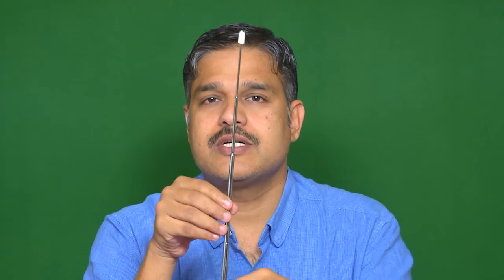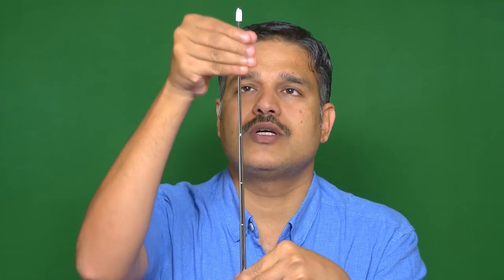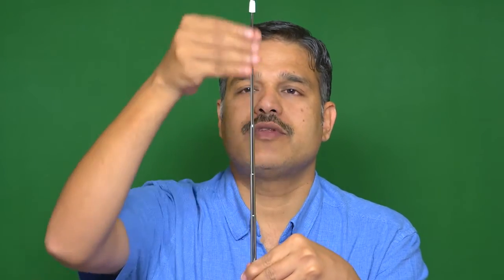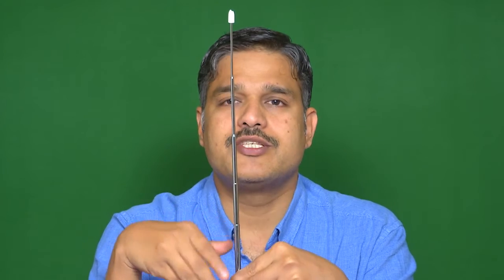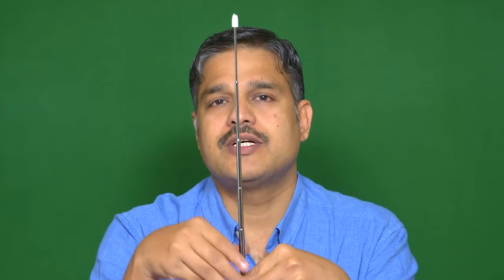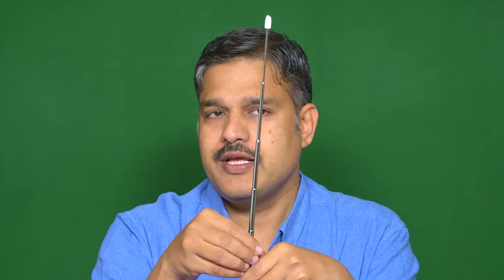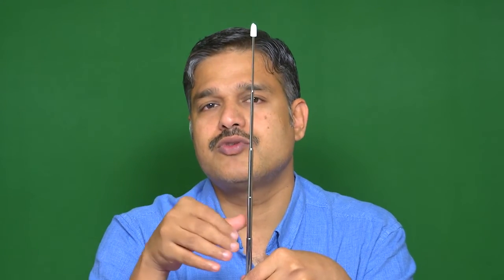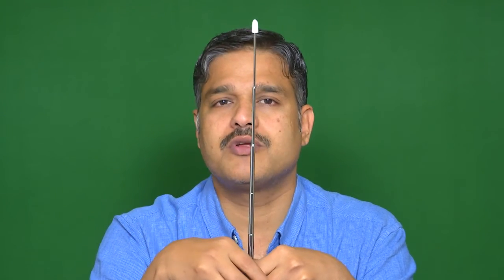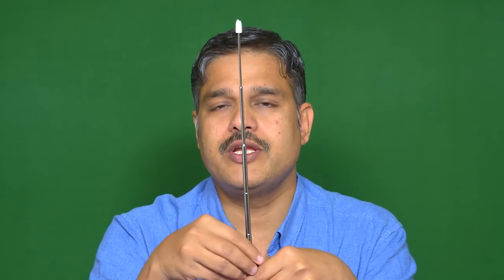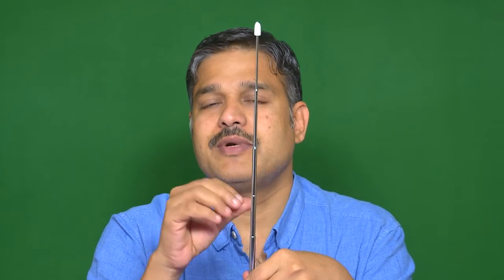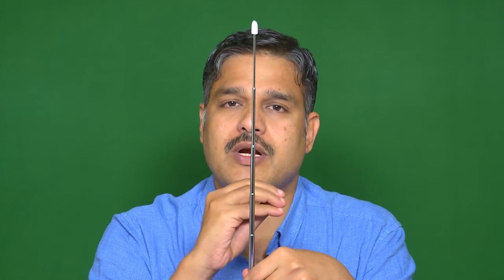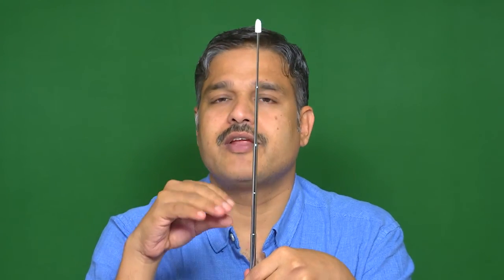But in continuous systems, mass is distributed continuously throughout the structure, throughout the height of the structure. For example, a tower or a chimney, a communication tower or chimney. For studying vibrations, or understanding the response to a given ground motion or any wind vibration, we need to employ different techniques, not the same technique as we have used in multi-degree of freedom systems or single degree of freedom systems.